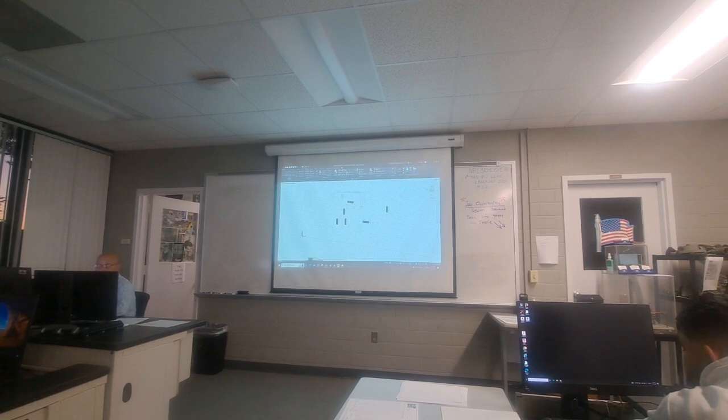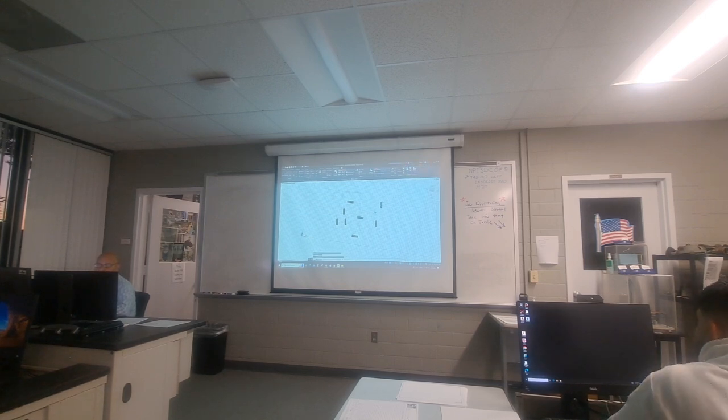Control-Shift-V, like what I told you about the border and title block, still copies them from the clipboard to your drawing. The biggest difference is with Control-Shift-V, they're locked in together as a block, so they are considered all one unit. Even if they are not touching, you cannot do something to one of them without affecting the other one unless you go X and space bar and explode those objects. Once you explode them, now they're individual entities.